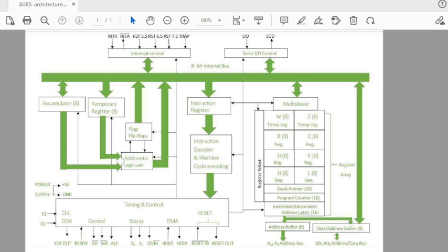The ALE signal is an active high signal. That means when we provide 1 on this signal, then this signal will work. And when this signal works, then AD0 to AD7 addresses will be transmitted from the microprocessor. You can see the name: Address Latch Enable.